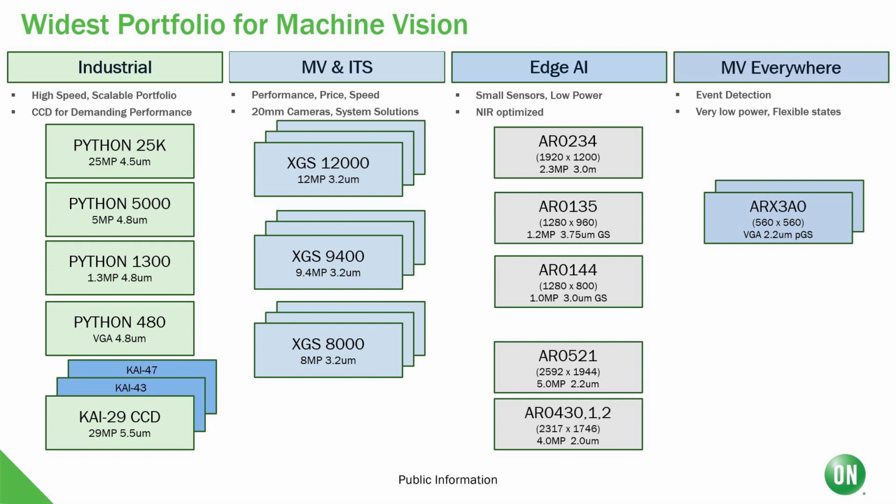For your smaller applications, which we refer to as Edge AI, your smaller optical format, we offer 3 image sensors of the global shutter type: our 2 meg and our 1 megapixel third inch, and our 1 megapixel quarter inch, the AR0144.